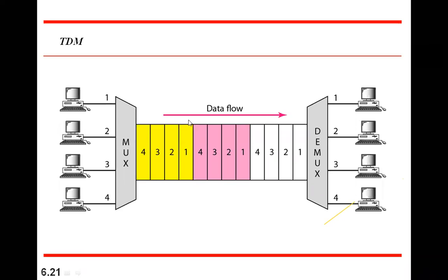The entire channel is available to each user for the duration given to him. Whereas in a frequency domain system, part of the frequency is available, but all the time. Please remember that. Here, the channel is available for a short duration, just the time allotted to him, but the entire channel, the entire bandwidth, is available to him.